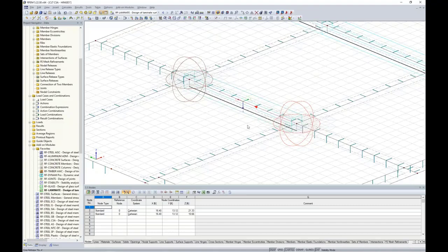Now this is not going to take care of our singularity problem, but what it is going to do is make this high stress location available to us in a result in a much smaller location than rather us using the 1 foot width of the global FE mesh settings. So we're kind of isolating the issue into a smaller area.